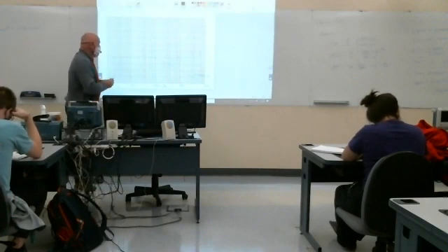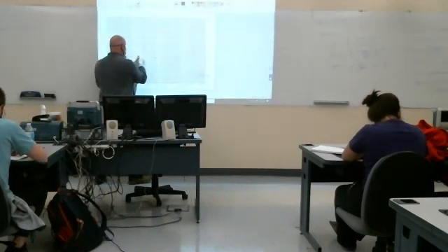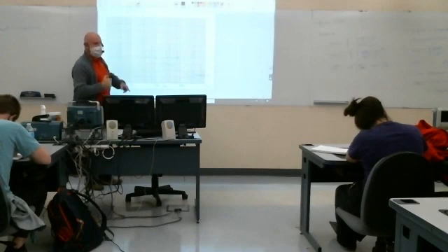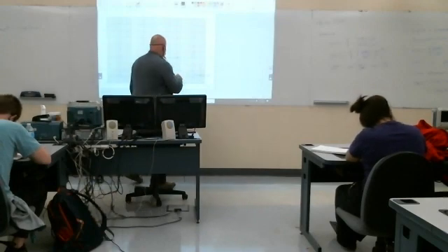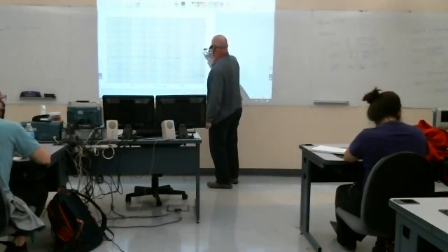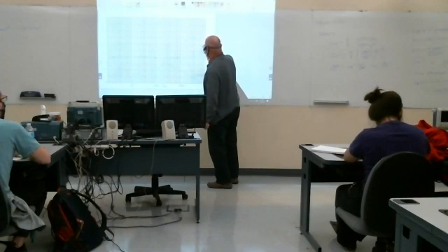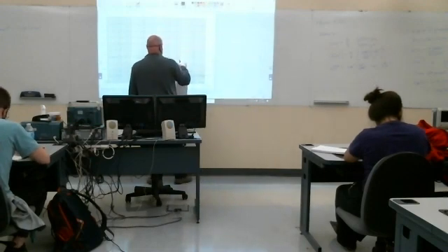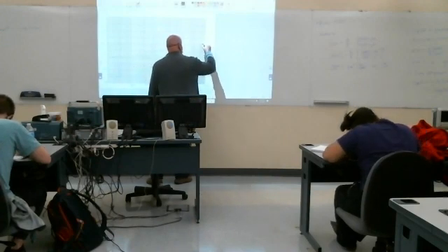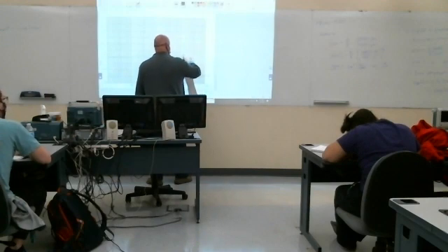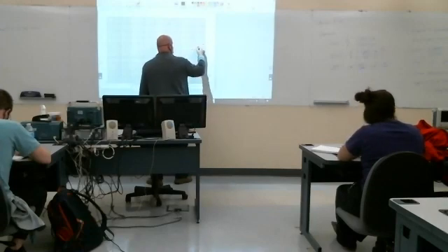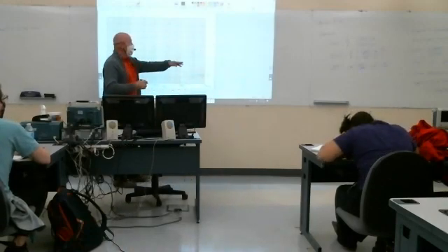The zero term, remember it's this. Okay. Now when I get out to the zero, it's going to go up at 20 dB per decade. Okay. So here it's 8,000. Out here at 80,000, it's going to be 20 dB higher. So that'd be right there. So I could lay my, if I had a ruler, I screwed it up right there. I'll do better this time. Okay, and that line would continue forever.